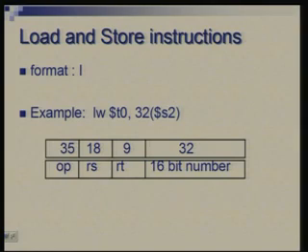You have to take this number, okay, which is a signed offset 16-bit number, and contents of this register, add the two and apply that as address for the memory, okay. And this field defines the register which will exchange the data with the memory depending upon whether it is load or store, right. So, we need to look at these two registers specified by these two fields and a constant.